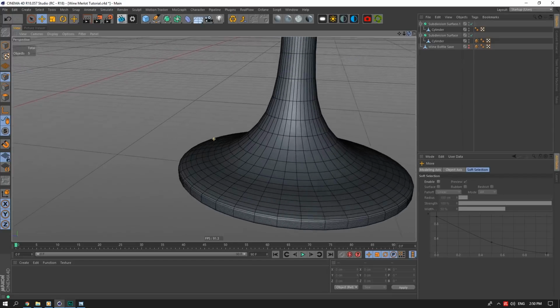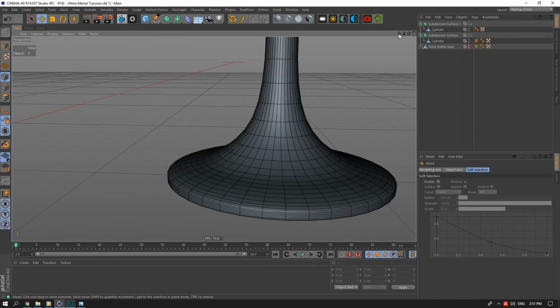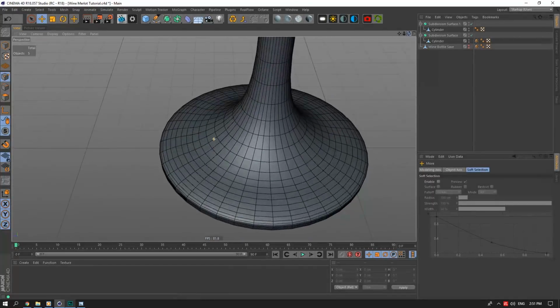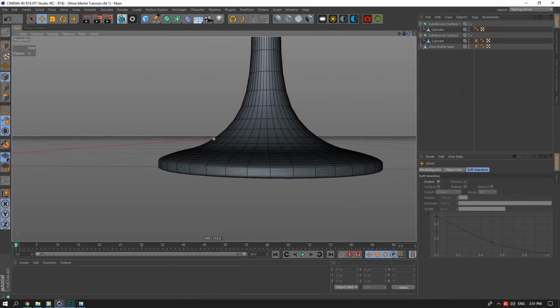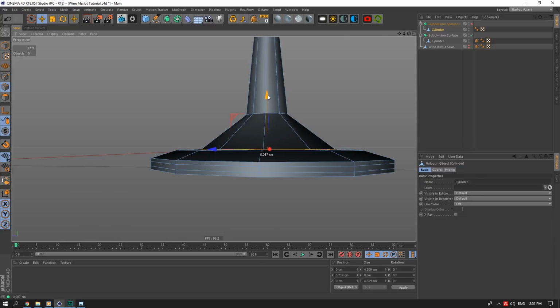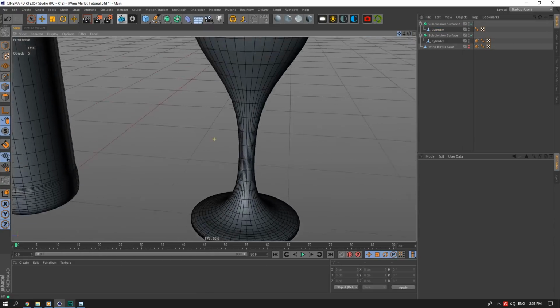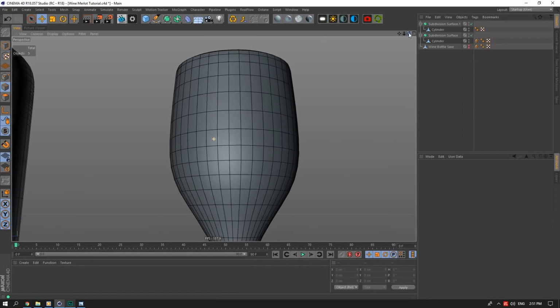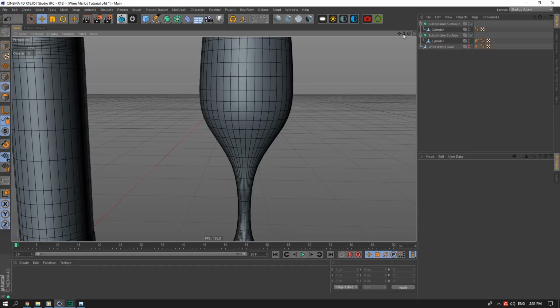And our subdivisions are looking very good. They're all purposeful, except down there and other minor cases, but we don't have more subdivisions than we need, and that will really help with our rendering in the final, because Octane does not do very well with glass materials, specular materials and stuff like that. So having as many subdivisions as we need, but not too much, will always help.